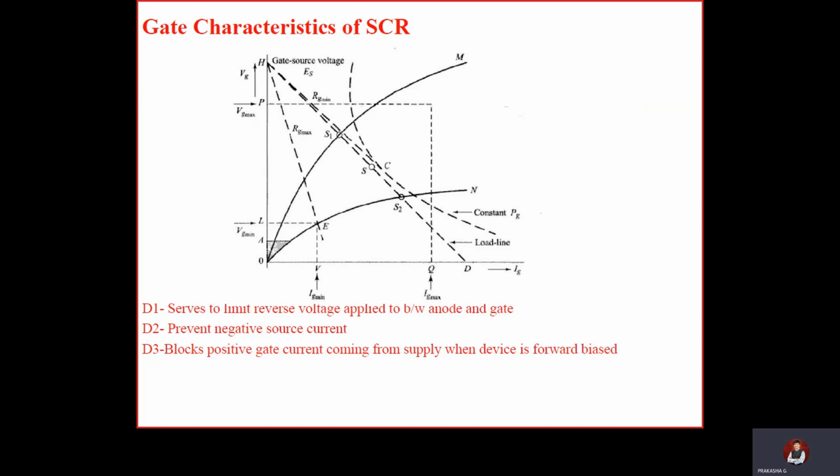Once the voltage crosses 8 volts, which generates 8 milliamperes, because I have a 1 kilo ohm resistor there, 8 volts across 1 kilo ohm gives 8 milliamperes. Once you have 8 milliamperes, only then is your anode cathode going to give some variation: voltage drops and current increases. All of you have done that on your instrument, the gate characteristics of your SCR.